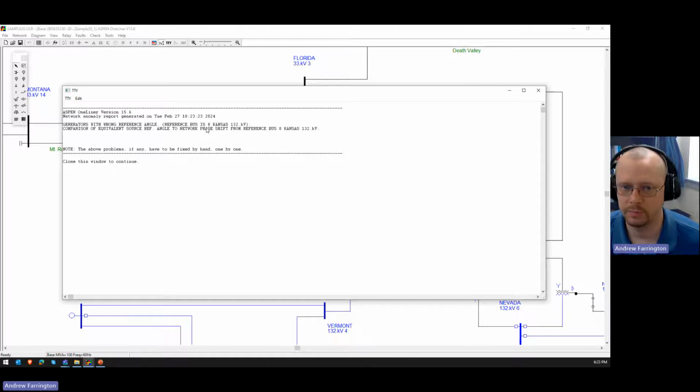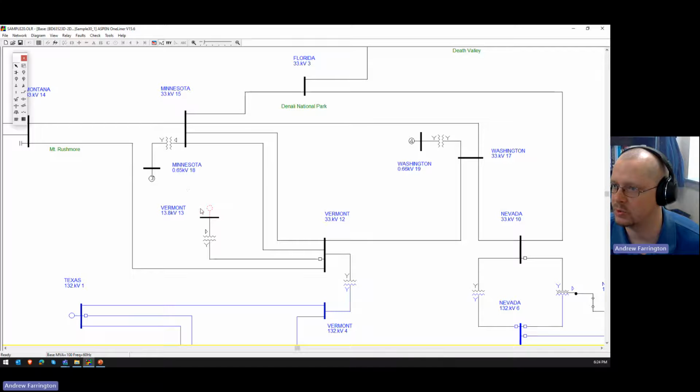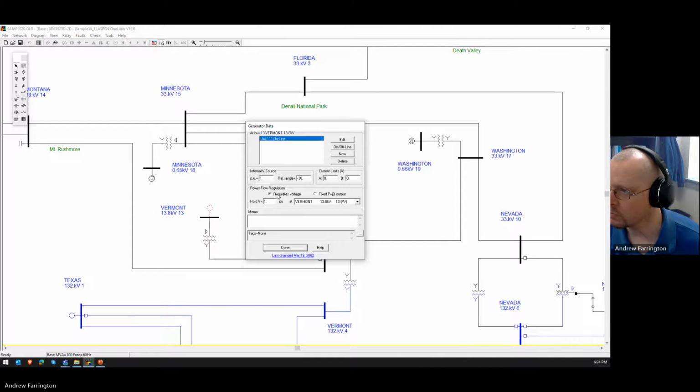You can just pick 0 and then check to see if the generator that's connected to that you've just modeled has the right reference angle or not, and it'll tell you what the right reference angle is. But you need to make sure that that's set correctly. So that's really important, and it's not obvious if you just look at this parameter. At least I would go, what reference angle? I don't know. What does it need to be?